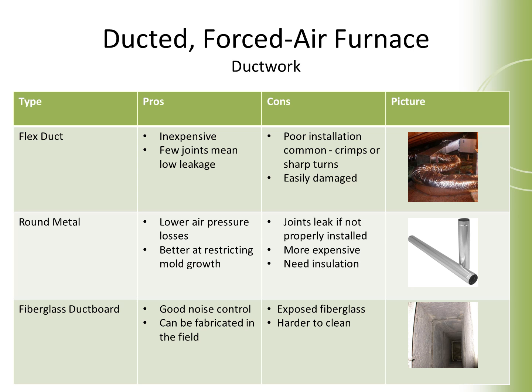Round metal ducts are good because they have a lot less pressure loss, and because of their smooth surfaces, they also don't collect as much dirt or moisture. Unfortunately, when they do leak, they're harder to fix, and they are more expensive to install, and they also require insulation.